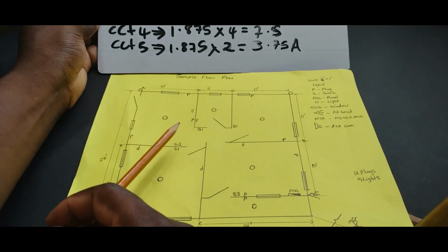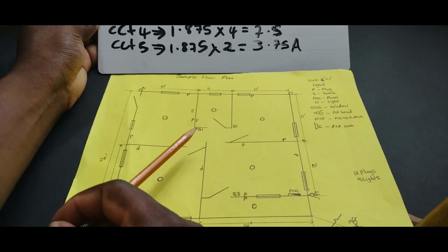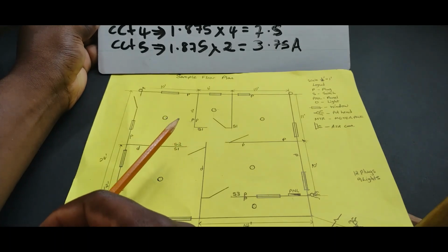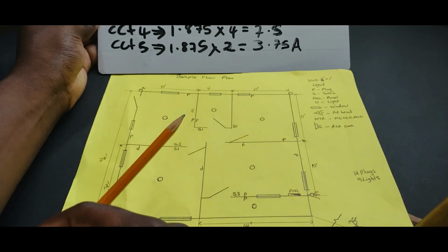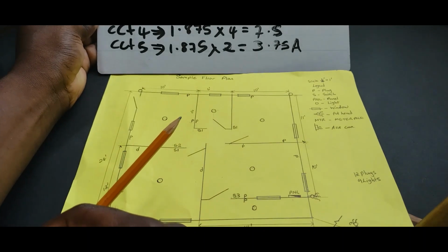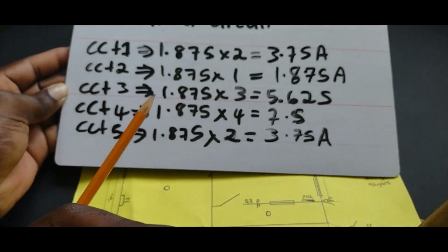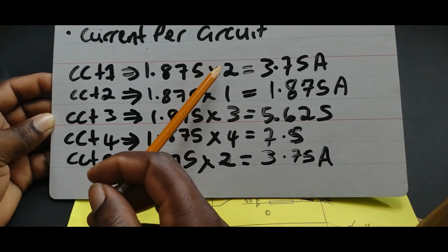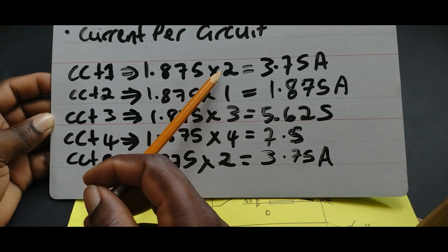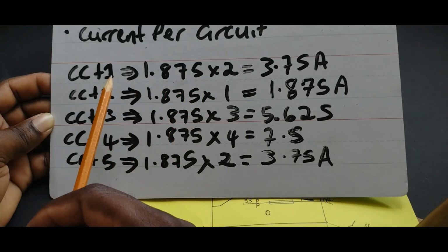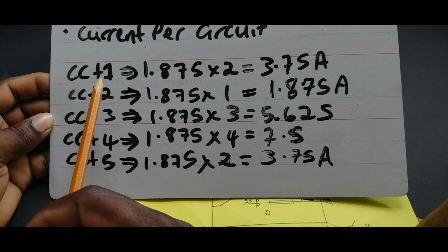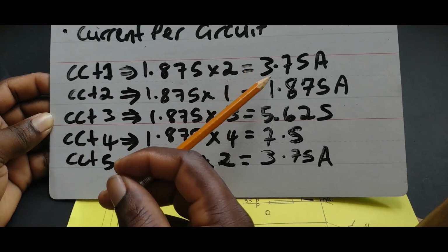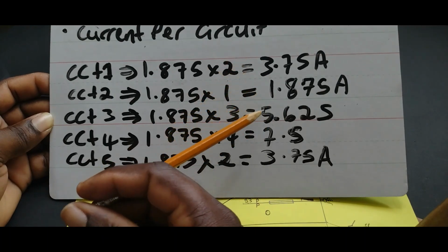We won't be doing it that way. We want the bathroom to be off when its breaker is off, and the kitchen counters to be off when its breaker is off. So here, bathroom, kitchen counter. These are for the kitchen counter. And for the purpose of knowing the numbers, this is what each circuit will be joined.